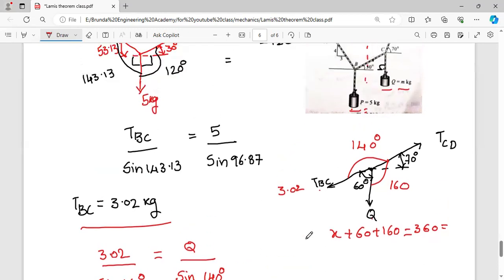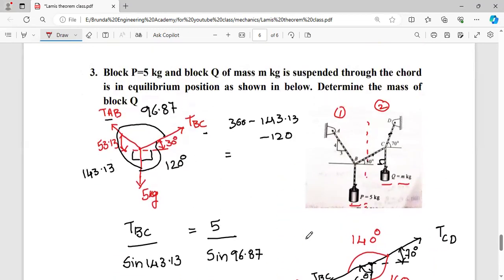So in this way, we can solve the problems. If you observe this procedure, first of all, you have to completely study the diagram. From that, you have to eliminate the supports, and indicate the actions and reactions. Then we can get the free body diagram and identify it very clearly. You have to identify the angle between the other two forces. If you make mistakes while identifying the angles, then your answer may be wrong. So you have to practice a number of questions on Lami's theorem.